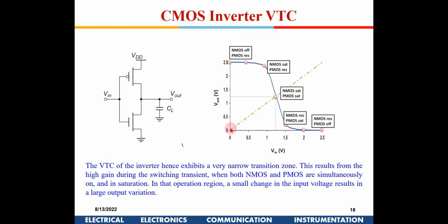Okay, and then we define something known as inverter switching. If you draw a curve like this at a 45-degree slope, wherever it intersects this curve is known as the inverter threshold. At this particular inverter threshold, Vin is equal to Vout. Is the inverter threshold definition understood? I think there's one more slide on it also. Otherwise, is the VTC curve okay with all of you till here?